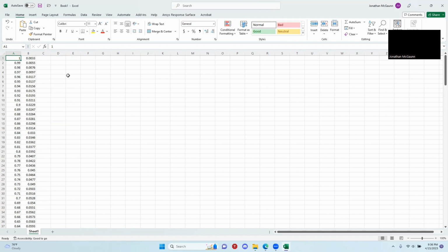I think it's a little bit easier just to apply a scaling factor in Excel and shift all of your coordinates to that scaling factor. So when you upload it, you don't have to worry about manipulation. Granted, if you need to do more hardcore manipulation, you can learn that other technique, but just for simple analysis, we're going to go with this method. So right now, this is reading technically 1 millimeter, and this is 0.0033 millimeters. So we're going to scale that up to 1 meter.